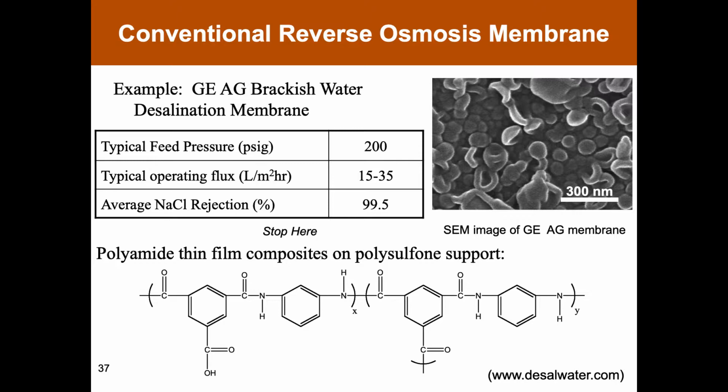They have a very similar structure to the one that I showed you before. And if you recall the mechanism by which these membranes are formed, it's the metaphenylene diamine diffusing through this oil layer to react with trimesoyl chloride at the oil-water interface. And that creates this irregular or nodular structure on the surface of these membranes that sometimes is attributed to fouling of the membranes.